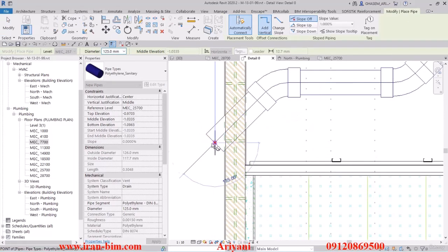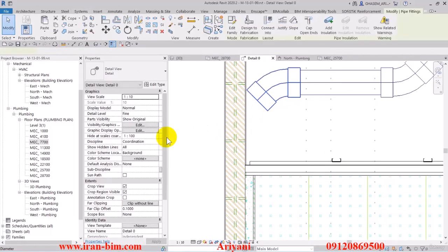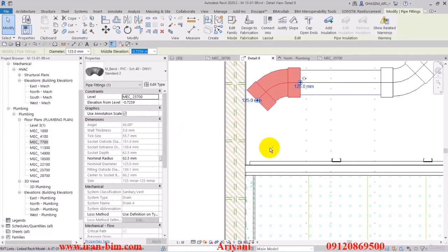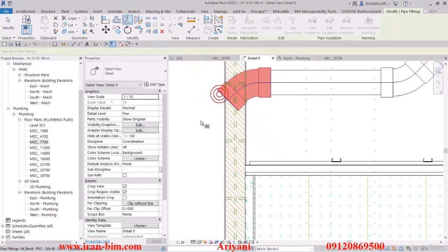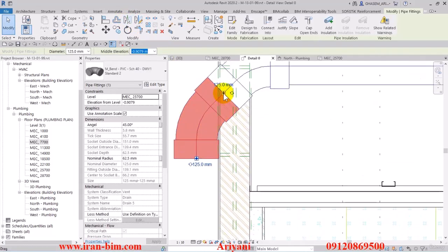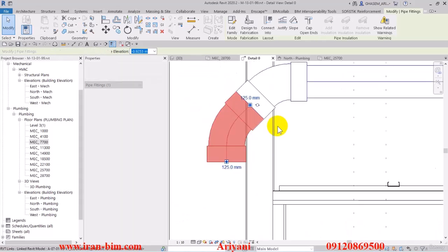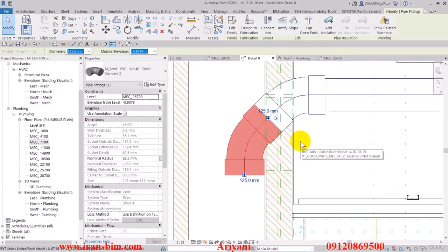pipe option, and then draw a pipe using a 45-degree angle. So select the pipe piece and delete it. Then we'll select the fitting and move it here to the left, and then I'll mirror it on this side. Now we hit tab to move this and then bring it forwards a bit to get it just right.